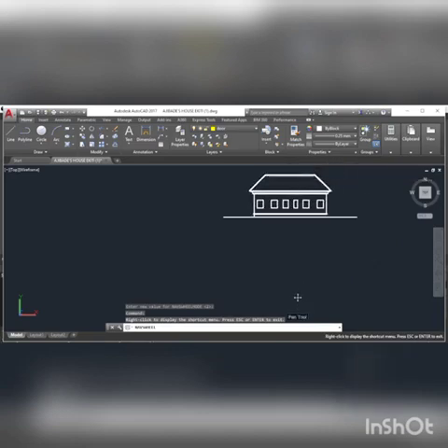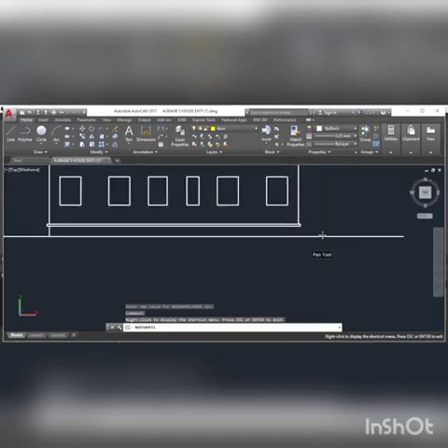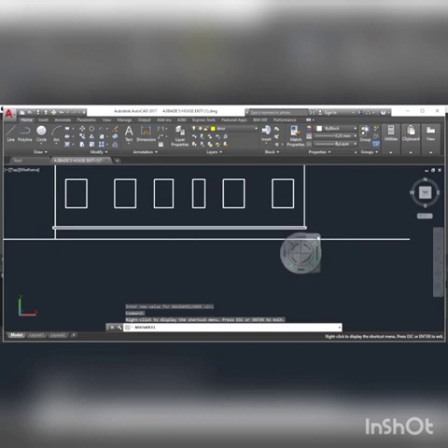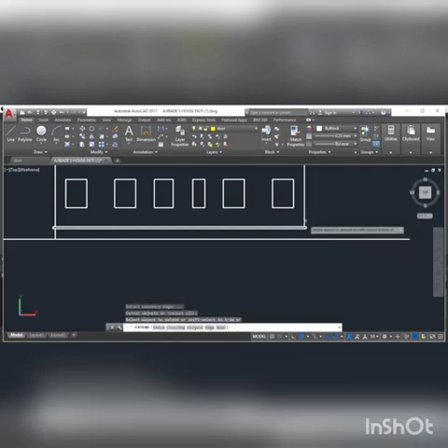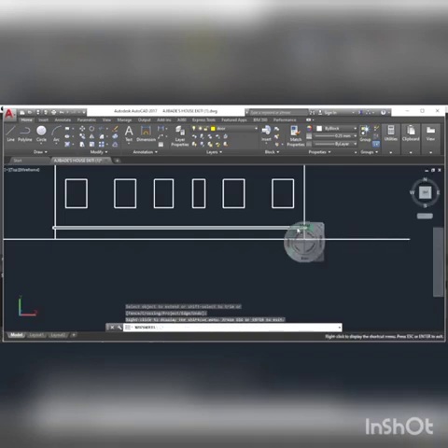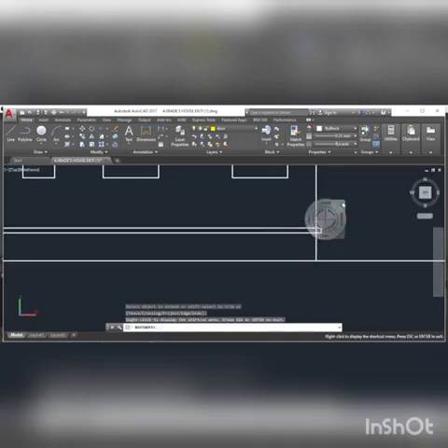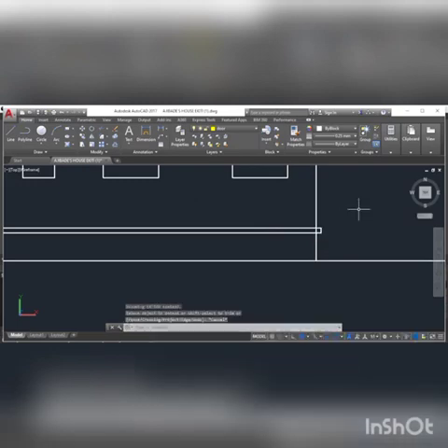So like I said, we have a line not cutting across, so we just extend this, EX, enter. So we need to be careful with all these detailings. Very important. If we omit any line, we'll have to manually impute that by ourselves. So escape, TR, enter. So yeah, we have that sorted out.